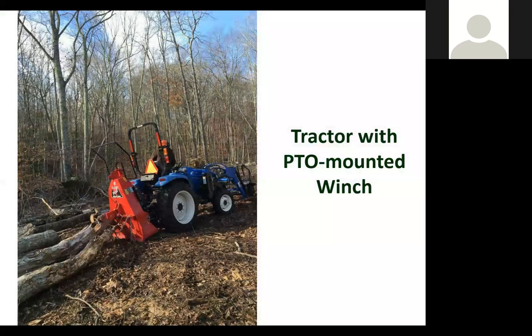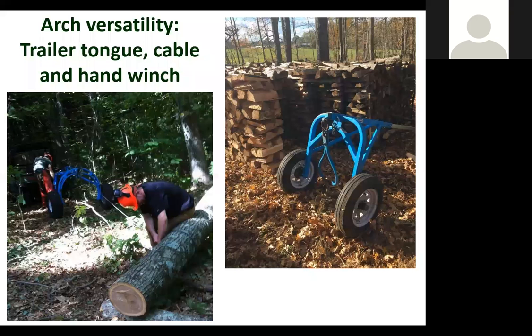The tractor mounted winch is one that has a little more capability in terms of volume at a time. Once again, the whole idea is to get one end of the log off the ground to reduce the friction, but you have a little bit more horsepower. And you have a remote capability in terms of having a cable that you can run out some distance to pick up the wood and drag it over to where the tractor sits. You don't have to back right up to the piece of wood that you're moving.